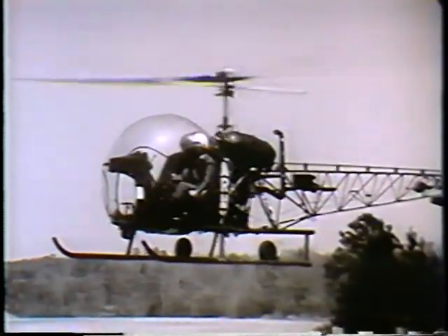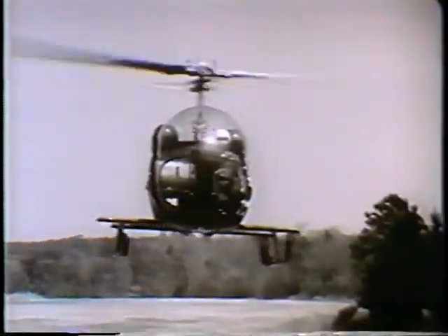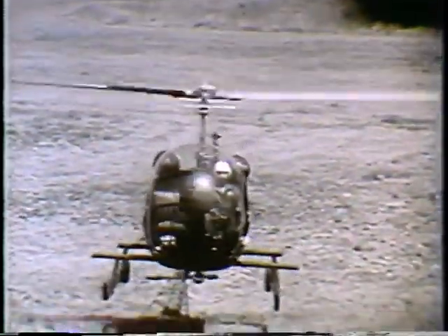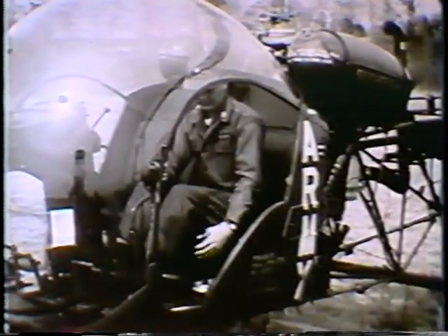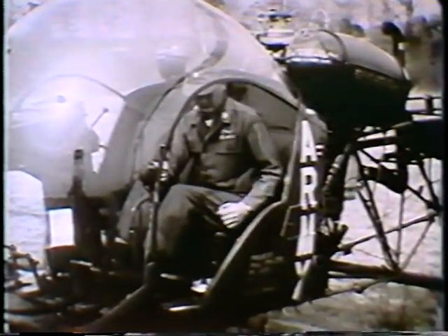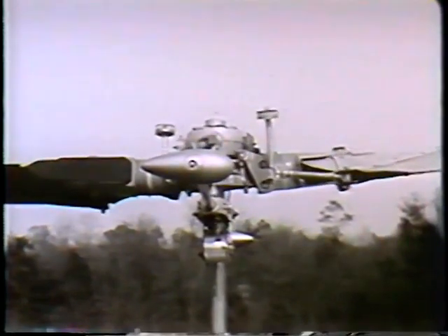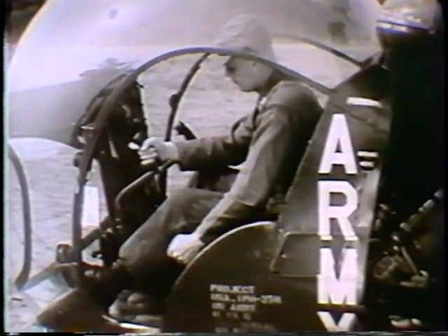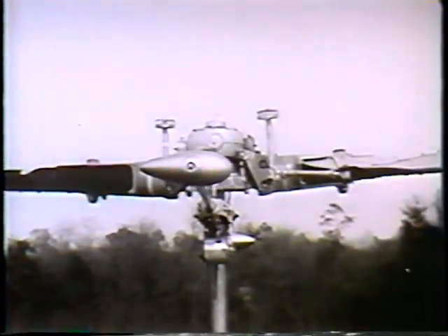As we pointed out earlier, a helicopter pilot varies his lift and achieves control of the helicopter not by varying the RPM of the rotor, but by varying the angle of attack of the rotor blades. By applying collective pitch, he changes the angle of attack equally on all main rotor blades in all positions. Through cyclic control, however, he can increase the angle of attack on one half of the rotor disc and simultaneously decrease it on the opposite half.